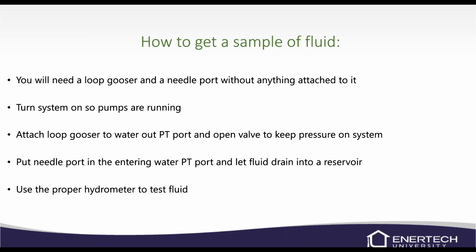So propylene glycol and ethylene glycol, you can buy those refractometers at automotive stores. And the methanol and ethanol, which is alcohol based, you can usually go online and look for a methanol refractometer on Amazon, or what have you. I think VG makes some refractometers. I think that's the brand that I have here at Enertech. If you're interested in that, we do have hydrometers that we sell at Enertech. Again, they're glass, so you've got to be kind of careful with them.